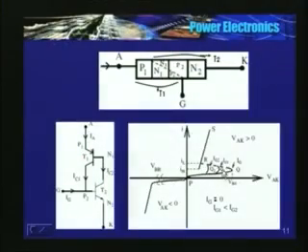Okay. So see, as the gate current increases, the voltage at which the device goes into conduction mode also drops. For Ig0, the voltage applied should be higher than VBO. VBO is forward breakover.